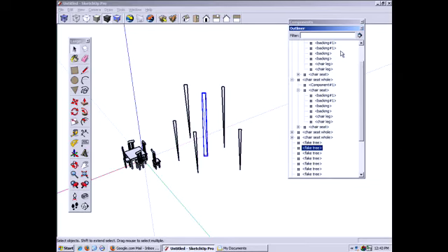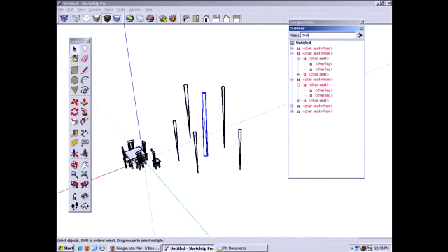You can filter this. As someone mentioned earlier, you get a lot of stuff going on. Well, if you are much better than me, I'm terrible about naming my components and groups. But you can filter, so you can say, I need to get to chair, seat. And now you can filter it down just to get what you're looking for. So Outliner is actually pretty powerful, more so than what I'm showing here, but it's a pretty incredible tool if you're getting into a lot of depth with your components and this sort of thing.